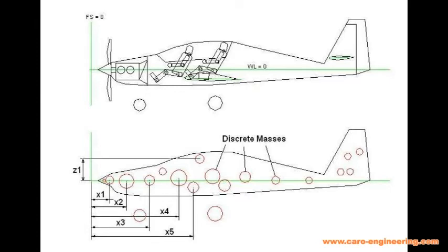To calculate the CG of the new fuselage, we need to have a pretty good idea of the weight of all components that will go into the fuselage and also the structure itself. So far, we have only used the x-coordinates or fuselage stations of the items we calculated. We will need to have x, y, z coordinates for all discrete weights and to eventually calculate the fuselage load.